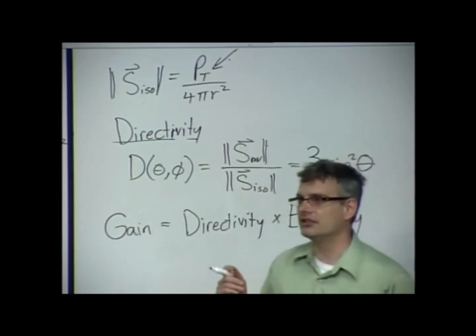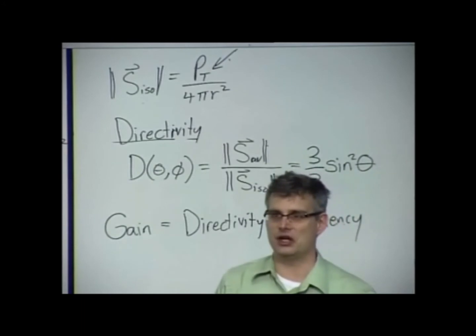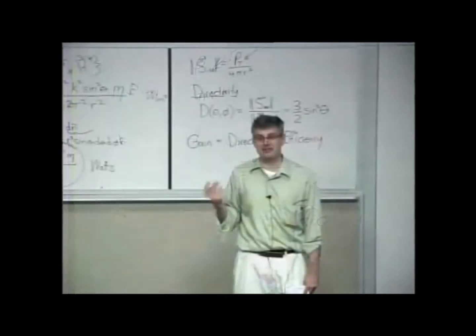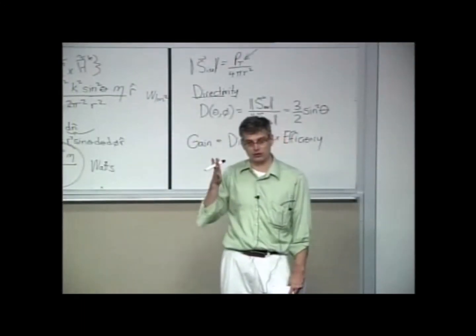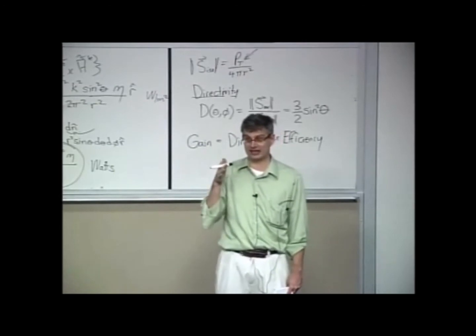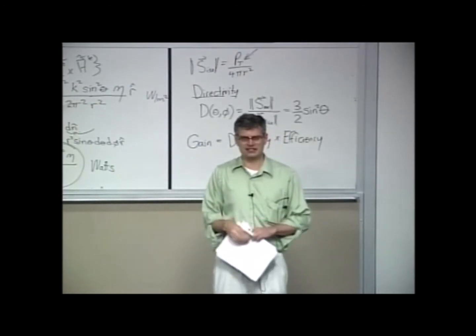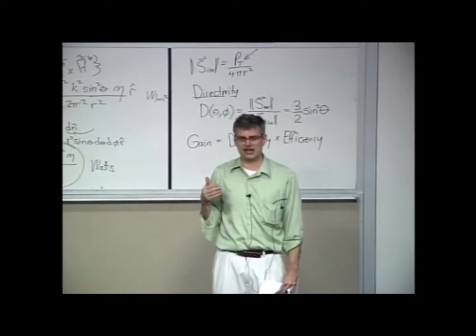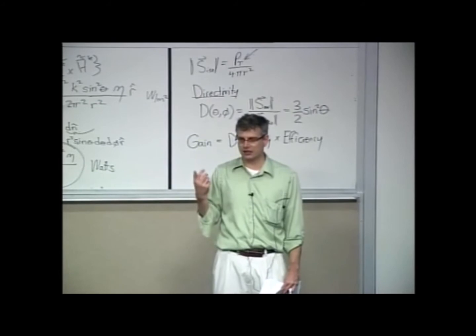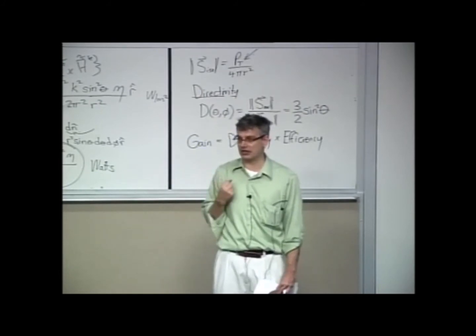In fact, there's a big debate often in antenna engineering about whether you should include mismatch losses. So, for example, your antenna, as we're going to show in a second, has an impedance. Impedance is measured in ohms, but it's not ohmic losses. It's really the transport impedance of the antenna, the ratio of voltage to current that it naturally accepts electromagnetic power from.